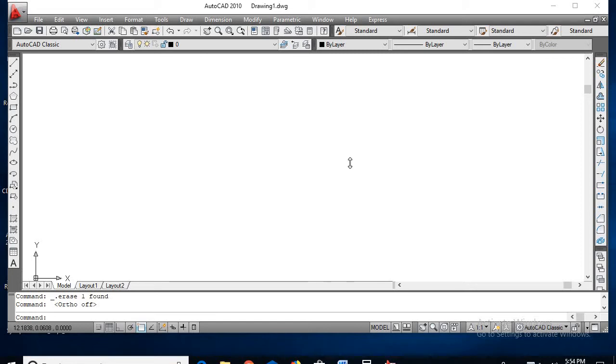Good evening to all. So let us go for DC armature winding, which is a simplex lap winding. Considering the first numerical, which consists of 30 conductors, 4 poles, and the type of winding is simplex progressive lap double layer.